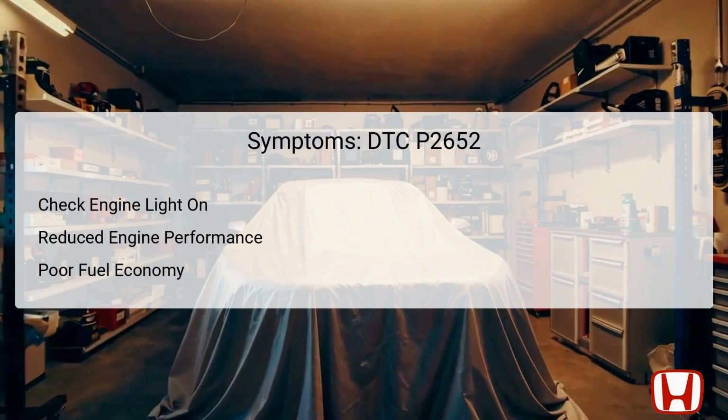Drivers experiencing DTC P2652 are likely to observe a few distinct symptoms. Most notably, the check engine light on the dashboard will be illuminated, indicating that the PCM has registered an error requiring attention. Furthermore, engine performance may degrade, as the VTEC system cannot operate correctly with faulty oil pressure readings, leading to potential delays in valve timing.